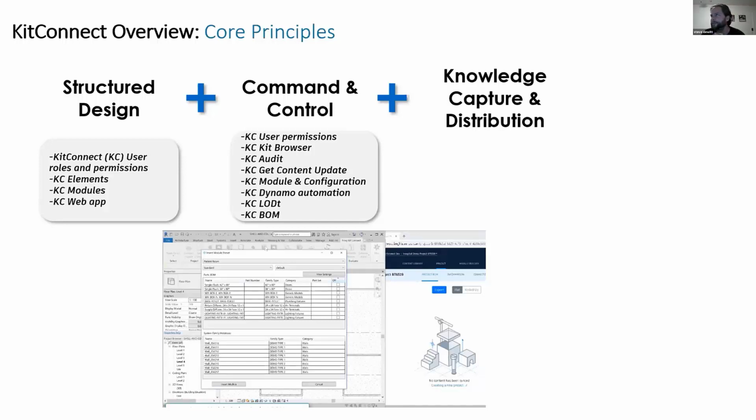Yeah, for sure. I've seen that error many times. Typically when we model something at a really small scale, we model it virtually. I know that sounds weird, but say you have a stud that's 8 foot long. I'm not modeling fasteners for that stud, but I know how many fasteners are in that stud because I know a length and I know an offset value for sheathing for that stud. So typically, at least for us, we don't model things to that small of a degree. We model those using conditional formats.